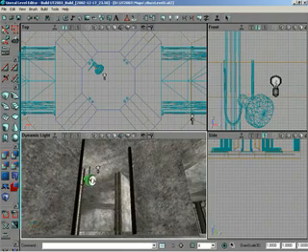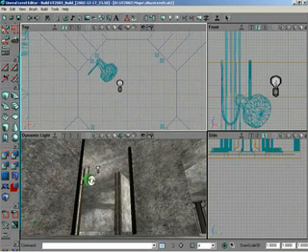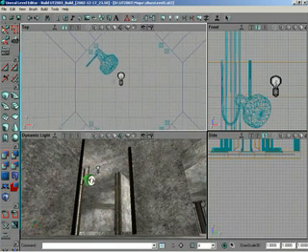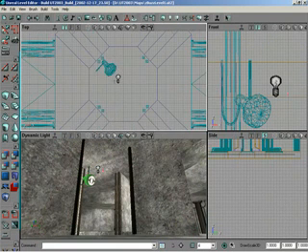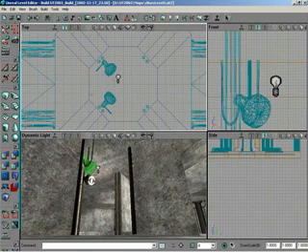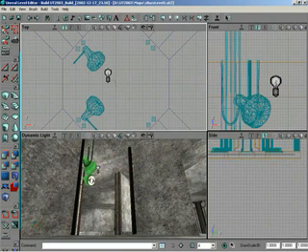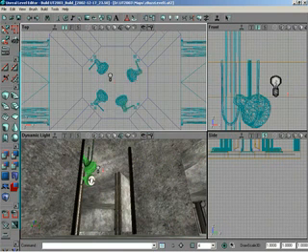So I've got the first one in place. Pretty happy with that. Right there. Now I can duplicate it. Move it back over. Center up the pivot. And move one over. Select both of them. Control W. Move them back. Place the pivot at the center. And then drag them around. So now I have 4 spotlights up at the top.